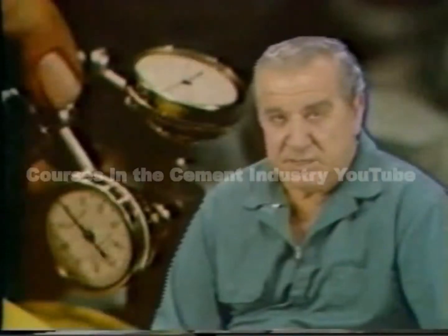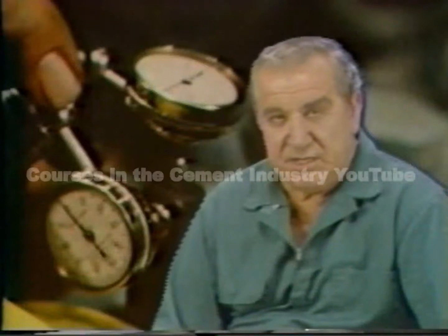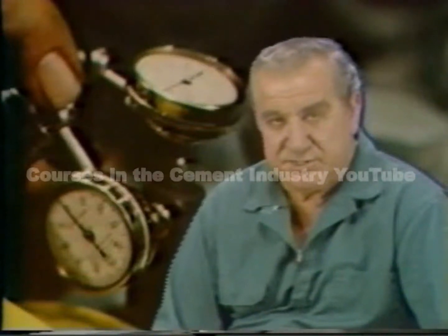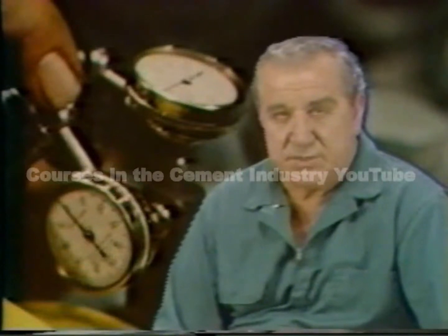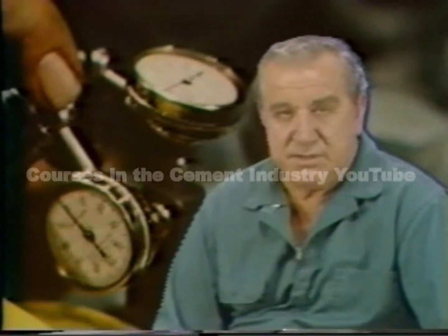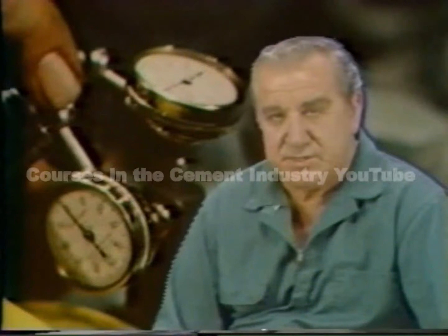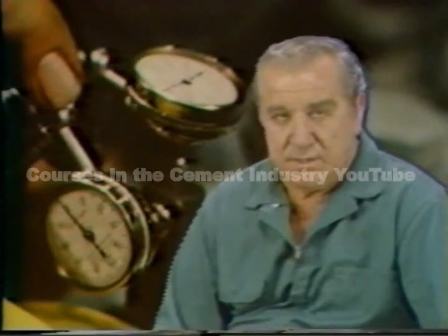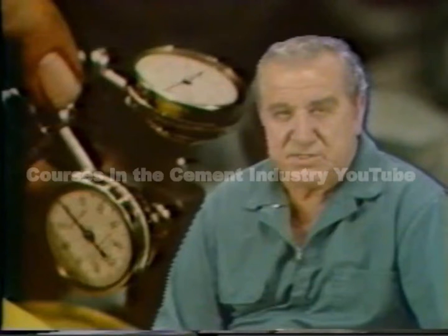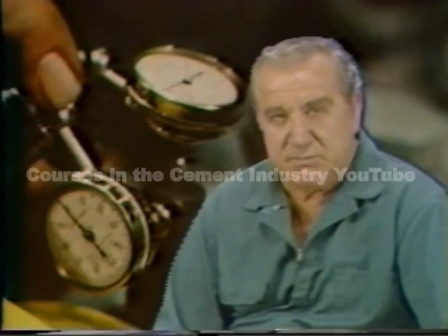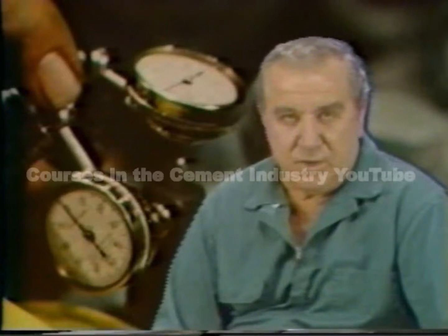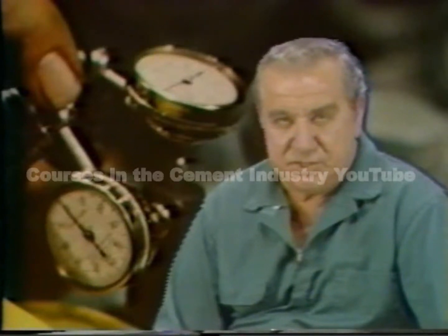In the last segment, the technician installed the dial indicators on the pump and motor shafts. He also verified that the mounting brackets are rigid by rotating the shaft to see that the dials return to zero. Now, before he takes his first set of readings, there are a few more preliminary checks that can be made. One is called a soft foot check.